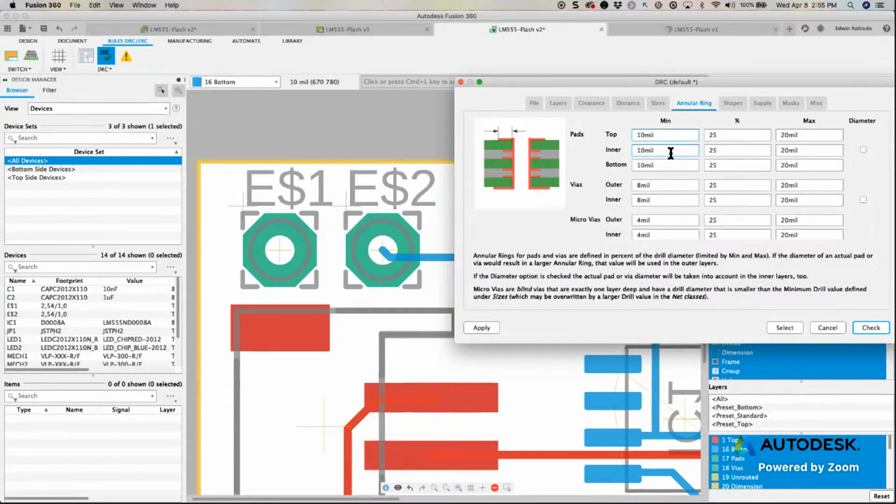Now, Jorge, I'll bring up one more observation that I've noticed on some boards, in which users have set up the percentage to like 1%, and they set the minimum and the maximum to the same value. Therefore, it's using that same ratio for all of the pads on the board. Not sure if that's a good idea, but I've seen some small boards where they just go ahead and do that. Yeah, they're in better control. Yeah, it depends on the board house, because if the board house specifies a minimum annular ring, then some users will do that. They'll just set everything on the board to that minimum.